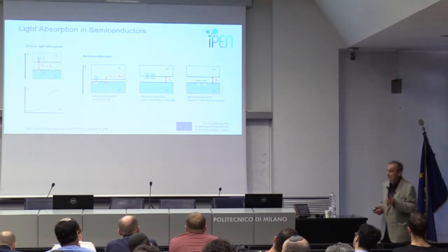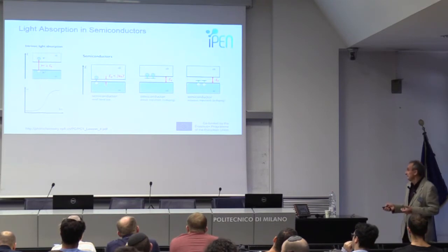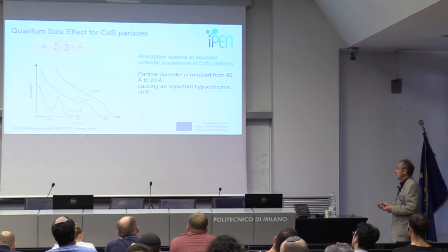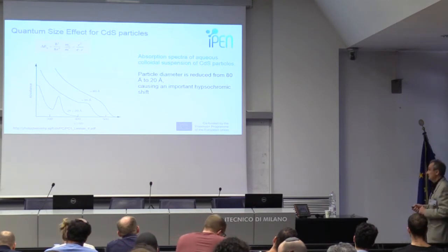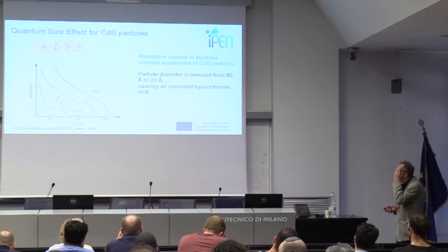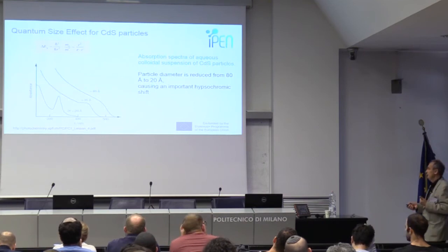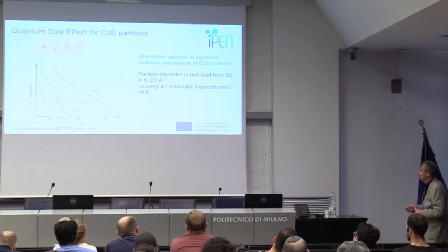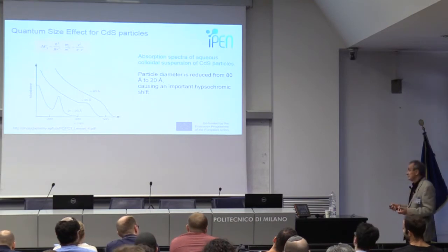In this situation, we will have nice absorption for engineering with lasers. We should not forget, and I give you this formula for estimating the quantum size effect: the estimation of the shift of the edge of your semiconductor is really simple, but works perfectly. If you try to make production with a laser on some semiconductor, you should remember: if you have volume material, nearly 80 angstrom, it's bulk material, or you have 20 angstrom, the shift is really huge. And if you think about the laser with which you would like to do manufacturing, it's of critical importance.